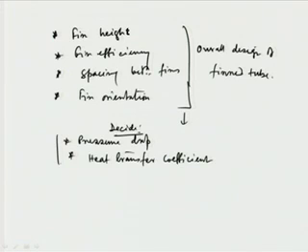And then, depending upon that, we can use, as we have discussed, that the rate of heat transfer Q dot is equal to U A delta T, and as I told in the last lecture, U is the overall heat transfer coefficient, delta T is the temperature difference, and A is the area of heat transfer. When the fluid is airy, say if we have to extract heat energy from air, or if we have to cool some body, then the air to metal surface heat transfer coefficient, or that of vapor or any gaseous substance to metal surface, is very small compared to the liquid side one.